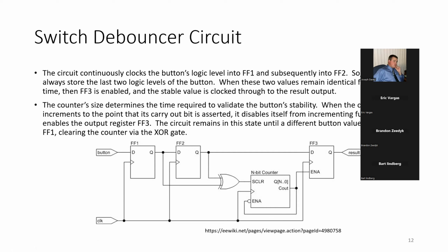If steady state, or sorry, if the output here is 0 and I'm getting 0 and the input is 0, 0 is transferred after 1 clock cycle. And at steady state, the two outputs Q0 and Q1 should be the same, the same as 0 or the same as 1.